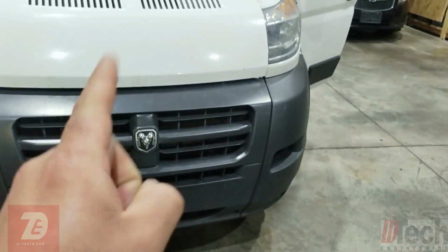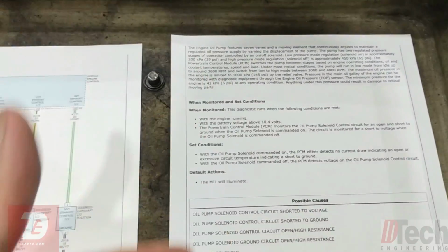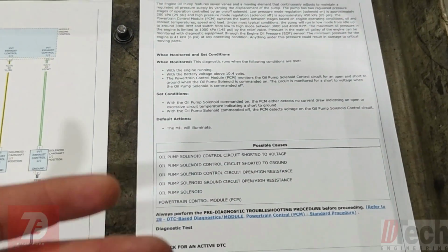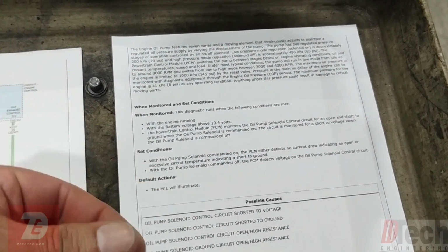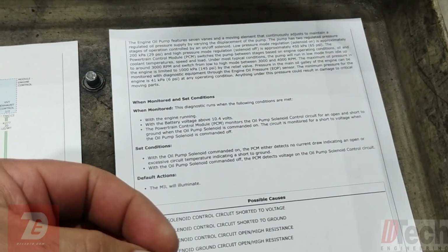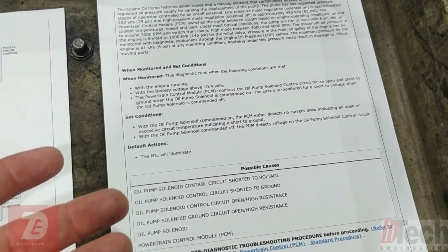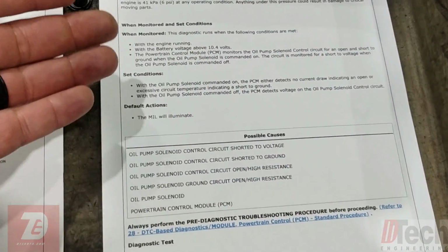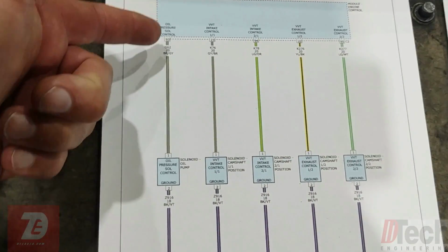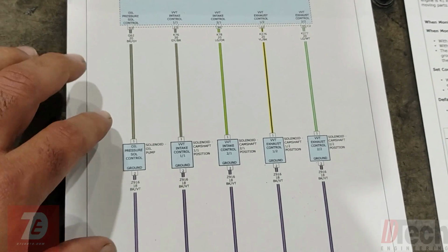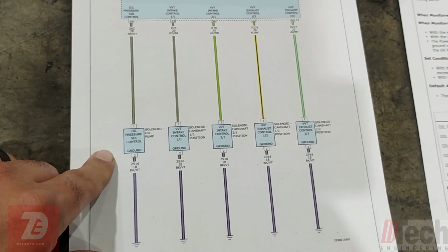that this keeps logging. Nowhere near that does it say that there is a physical oil pressure level issue for displaying the trouble code. It's basically literally telling us that it has to do with this circuit for the control solenoid for the oil pump.